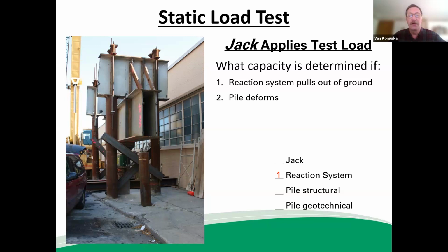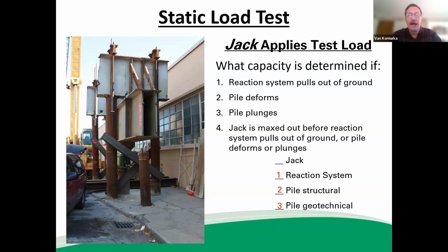What capacity is determined if the pile deforms? That is, it buckles or something like that. Well, now you've determined the structural capacity of the pile. What if the pile plunges, geotechnically plunges, moves down into the ground without being able to accept more load? Now you've determined the pile's geotechnical capacity. And here's the one that we're interested in. What capacity is determined if the jack is maxed out? You've reached the jack's capacity.